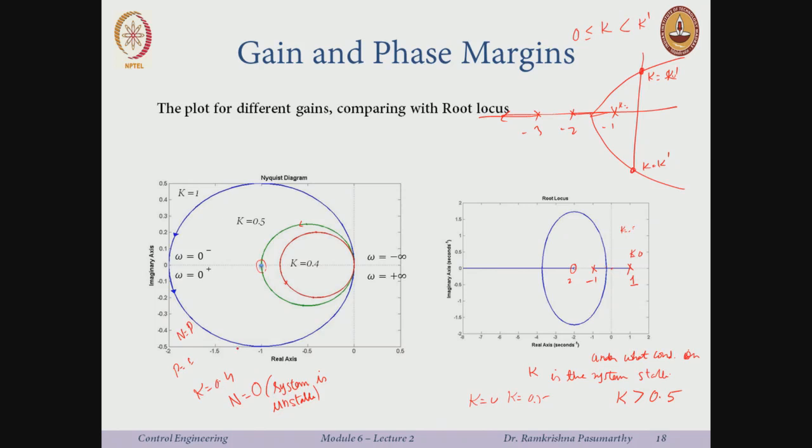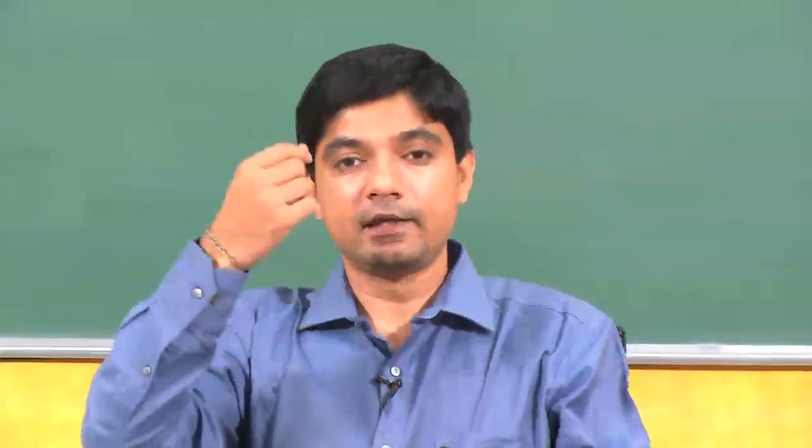Therefore, we call these systems systems with a negative gain margin. The earlier problems were formulated in such a way that how much can I increase the gain K before it becomes unstable. Now, it is the reverse. K equal to 0 is already unstable, K equal to 0.5 is already unstable, but there comes a threshold where after a certain limit I pull the poles back to the stable region and I am stable for all other gains.